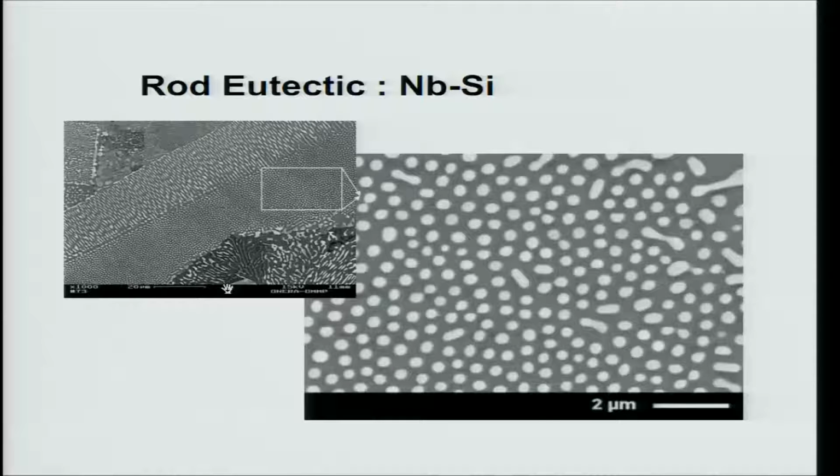You see here they look like a rod, okay, exactly like a rod. With the pen I show you, this is exactly like a rod. So, they look like a 3 dimensional rod and they are arranged in a very peculiar fashion. In some cases they are arranged in a hexagonal manner. So, there is an arrangement possible, and such a thing happens because of certain reasons. So, we have seen lamellar microstructure, lead tin, and this is a rod type of eutectic. Why such a change happens we will discuss later, but first you observe that there is a variety of microstructure possible in a eutectic system.